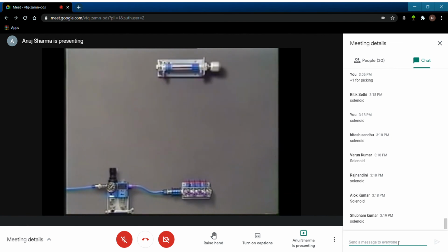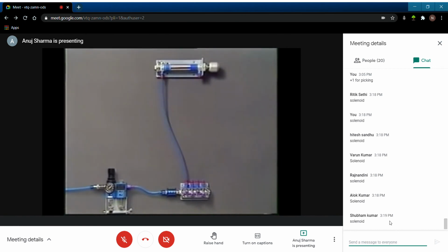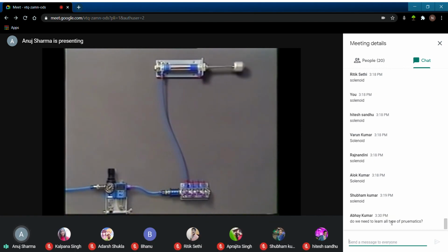components. The next step is to select the components that will actually perform the work. For this example, let's use a double-acting cylinder. If you connect the service unit directly to the cylinder, it will extend. However, this does not allow you to retract the cylinder.